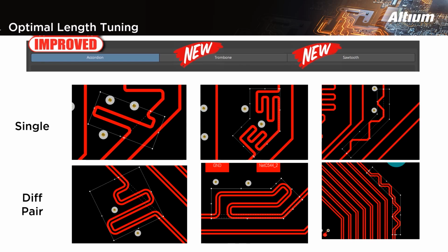If you're working with lower speed or lower frequency signals, you can get away with trombone tuning. You'll notice that there are multiple 90 and 180-degree turns in this trace configuration. Using curves for these bends is preferable to using hard right angles, in that it creates a smaller impedance discontinuity. There are a number of different movement and size change behaviors available, depending on where you click and hold on the sleeve.